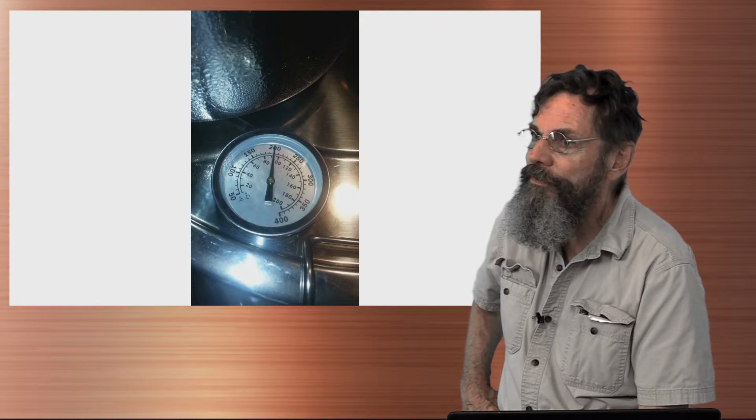If not, you can drill a hole in the top of the vessel and buy a sealable stem thermometer. They come in stem lengths of 2 to 4 inches, which is all you need for that. They have to be sealed into the lid with the 2 grommet seals they provide with it.